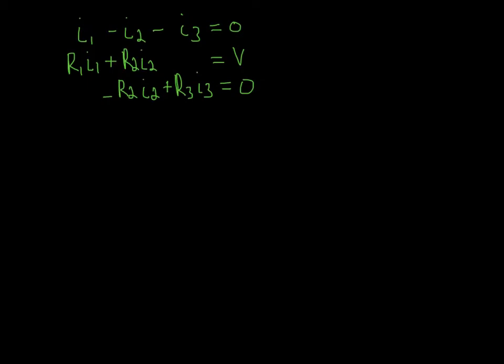Here are those equations written a little bit sloppily, but at least organized. So you can see that I'm organizing them by current. All right, these are like columns of current, I1, I2, I3, and you'll see why in just a second. Okay, so now, because this is a set of 3 algebraic equations, linear equations, we can use a matrix to solve them. So let's build that matrix.